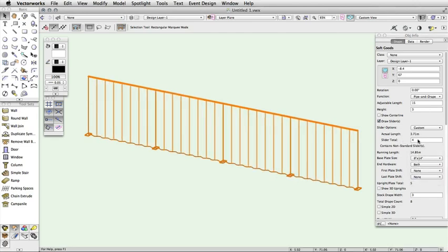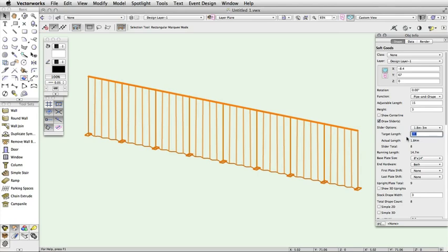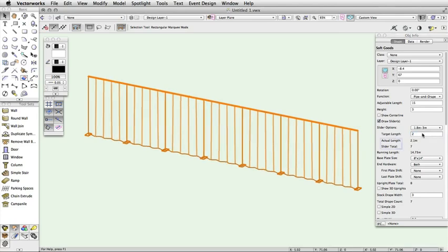If you select the standard slider range, enter your target length below. This will be the desired slider length within the range that you specified above. Actual length will display the calculated slider length. The number of panel segments created, listed as slider total, depends on the adjustable length of the entire assembly, the selected slider options range, and the target length specified.